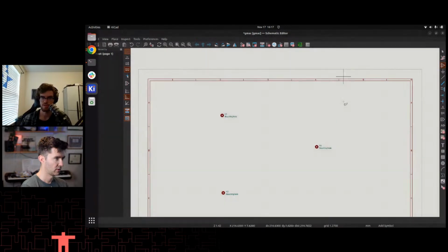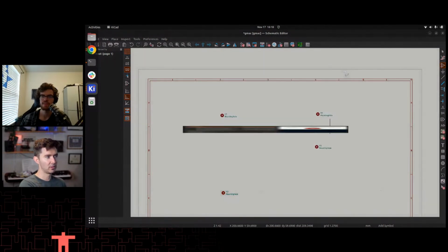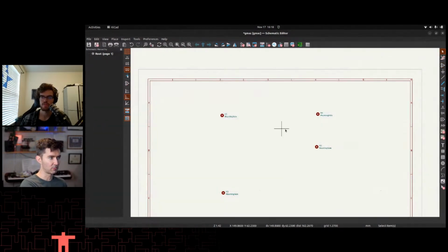As you wish. Can you? Okay. What you see there when you're clicking is that you still have that triangle there, which is really an op amp. It's showing that it's in the schematic placement mode. If you hit escape, it'll just go back to pointer mode. Yeah, gotcha. So escape is probably my most common keystroke in KiCad.